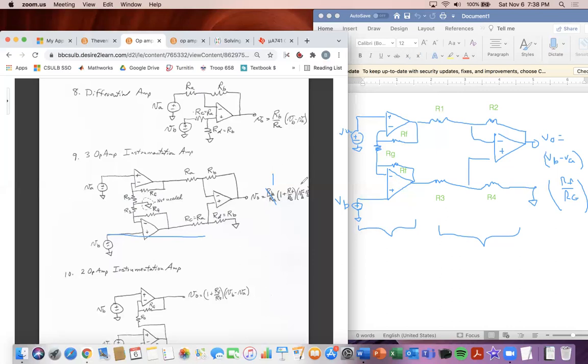Let me see. Okay, so I think he did a little mistake in this one when he gave it to us because it is a non-inverting amp, so the gain should be 1 plus RF over, yeah, so maybe don't rely totally. I would just say here, instead of using that, I would just do 1 plus RF over RG divided by 2, because that's for sure going to be one of yours at least, or you can split it up so then you have RS and RS here. He just combined these to make an RG here. And so then that's what he did.